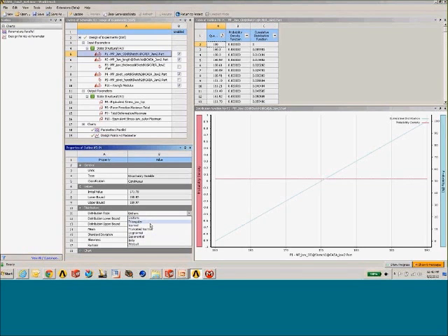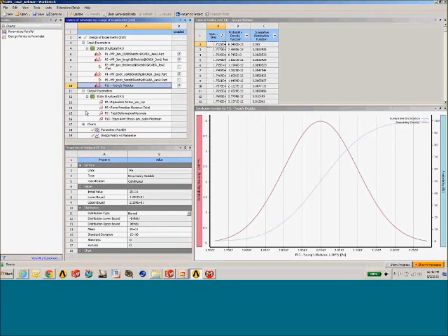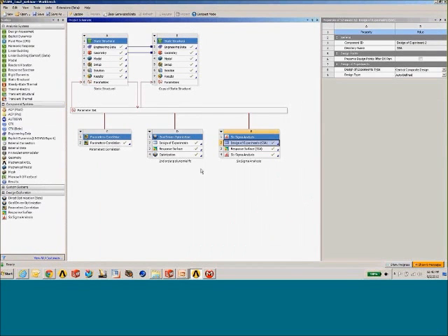So there's a whole number of different distributions that you can use that are valid for different types of analyses or different types of data that you have, and it all comes down to how much information you have about that particular parameter going into the analysis. So we set up that probability distribution of our input. We kick off the solution of our design points. We can go and generate our response surfaces. We do that in the same way that we did for the goal-driven optimization.